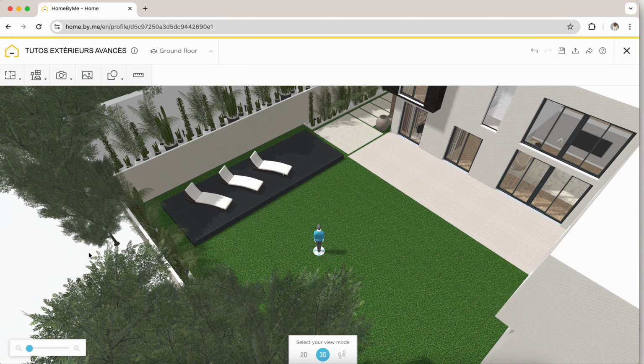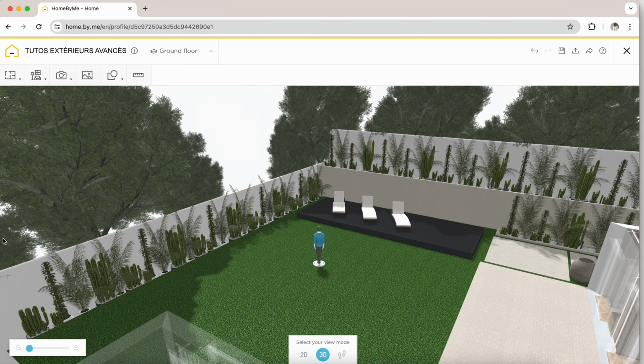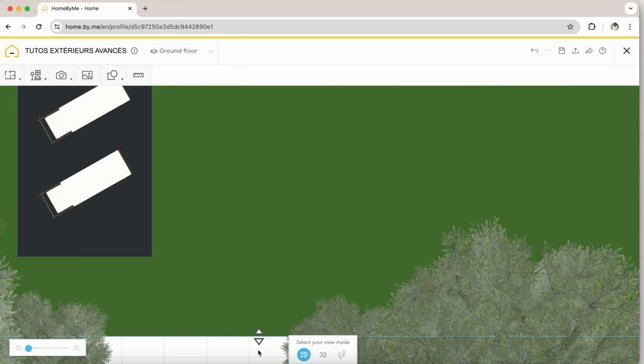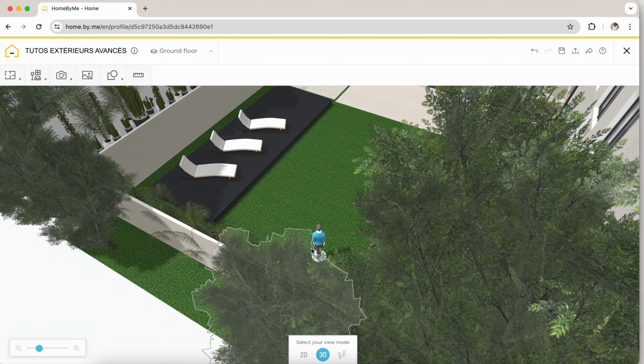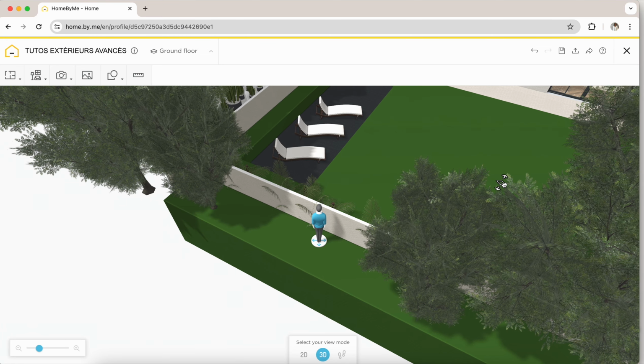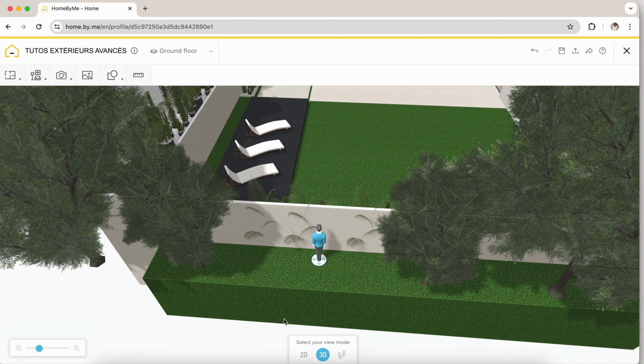You can also create swimming pools, but to create pools, you'll need a thick base already in place. Given that when we add an exterior, our floor is totally flat, it will be necessary, and I'll start by showing you how to create a thickness on our floor. By clicking on our floor, by first adding an elevation, and then using these designs to initially raise our floor and adjust the height by descending to level 0. This manipulation simply gives you a thickness that will allow you to dig into the ground to add a swimming pool.